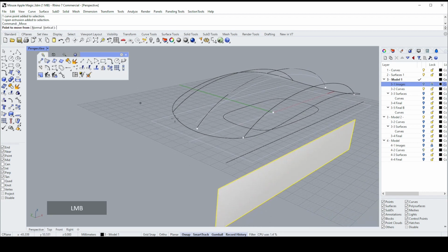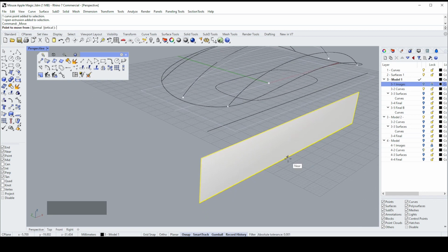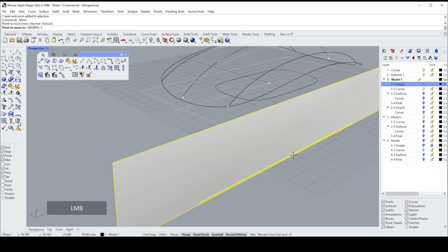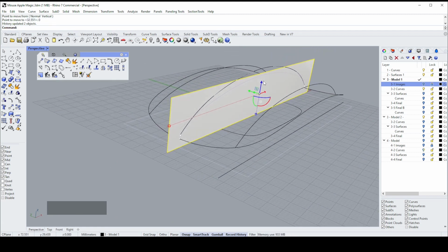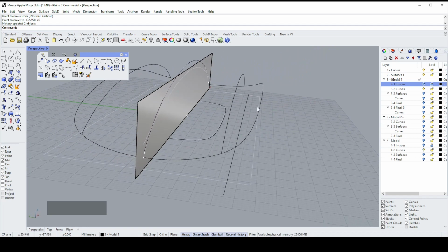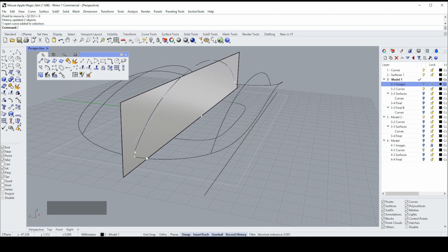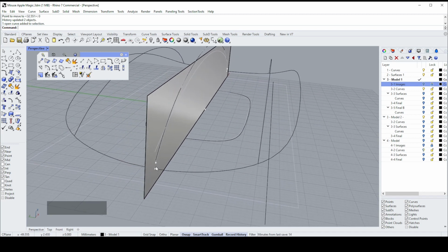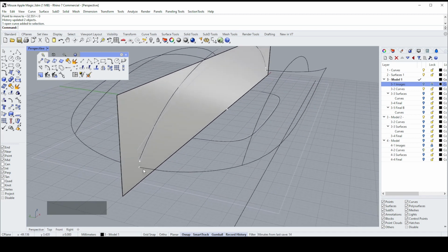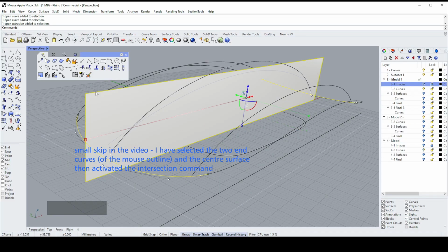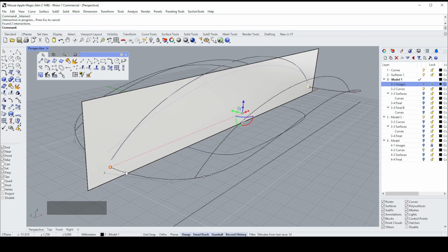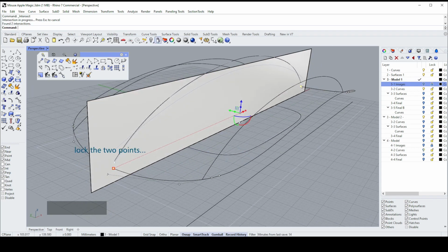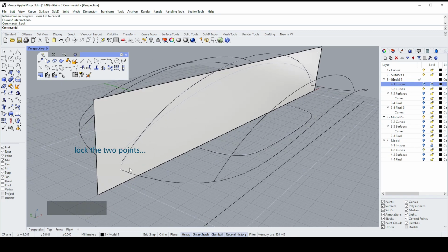So I'm going to say move. I'm going to get my snaps to find the midpoint at the bottom and then type 0 in, and enter. And there we go. We've got this lined up perfectly in the middle. And I know I created this curve perfectly around, all the curves around the center point. So I'm confident that I'm going to get a point which matches those. There, pick the two lines and the plane, come across here and say object intersection. And there they are. And then you lock them, so that they can't go out of whack.